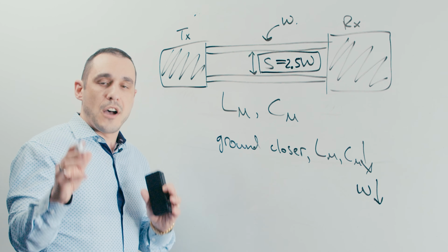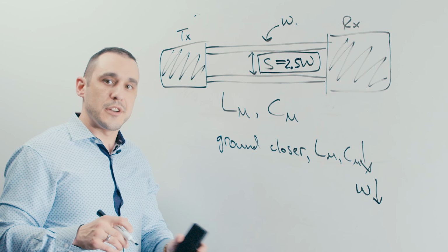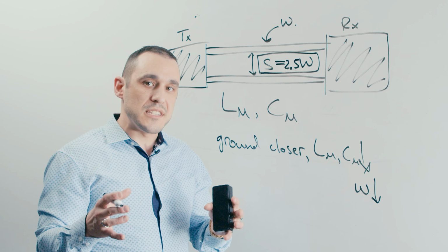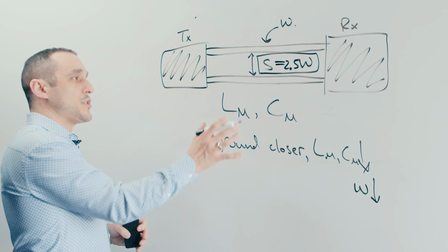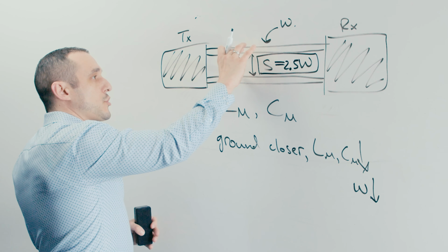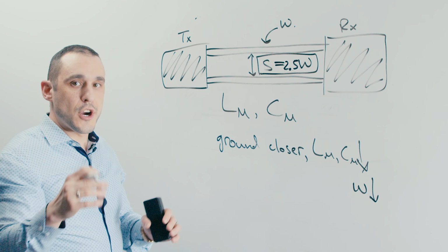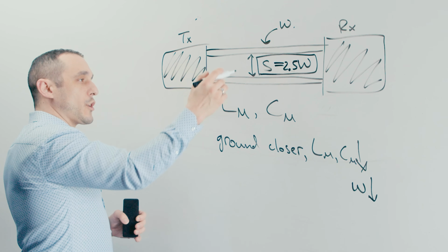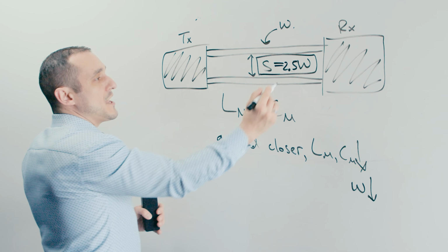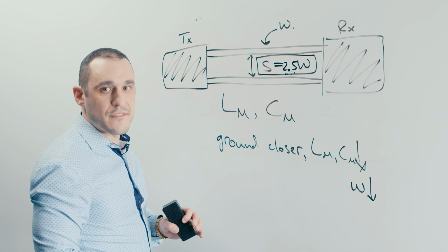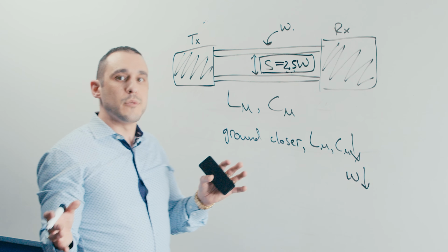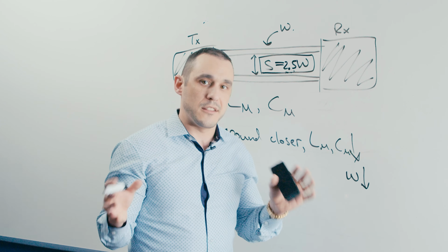Now this is something I've been talking about quite a bit at various industry conferences, and it's all about signal integrity on thin PCB layers. Because once you get to really thin layers where you have these traces very close together, you start to notice a lot of additional crosstalk. And the only way to overcome that crosstalk penalty is to increase this spacing value as a multiple of the trace width. So I'll definitely be doing more videos about this and talking about it on my channel.